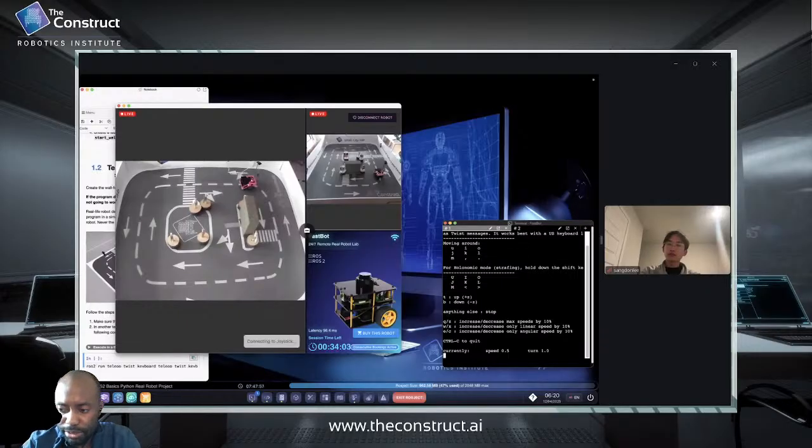As in, is there some specific criteria, like if you get this many laser scan indexes giving you a particular value, then it's pretty much a wall? Yeah, so at first I used a single index value, which was 0 degrees for the front index value. But when I used that, it was giving me too much offset between the minimum distance from the obstacle and the front index distance. So I used 20 degrees. I don't think I understand what you meant there. So you said when you used 0 degrees as the only index you consider, what happened?